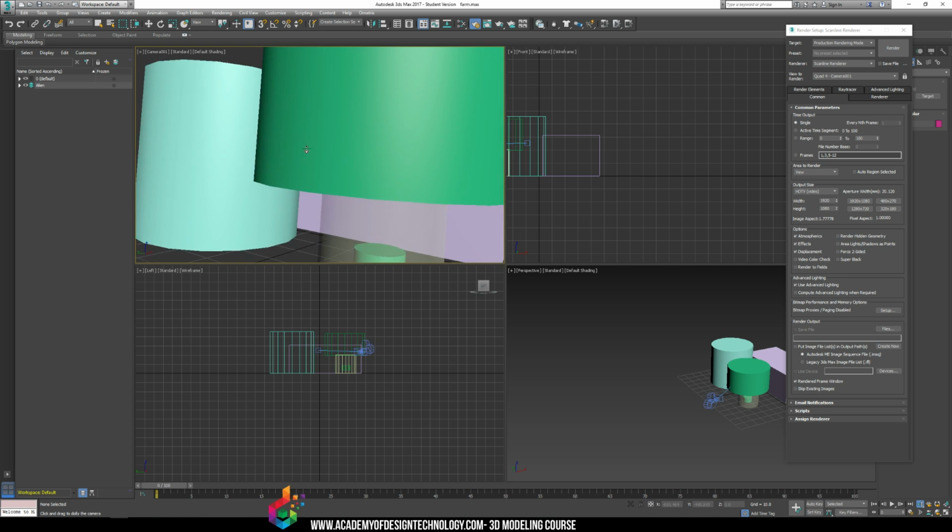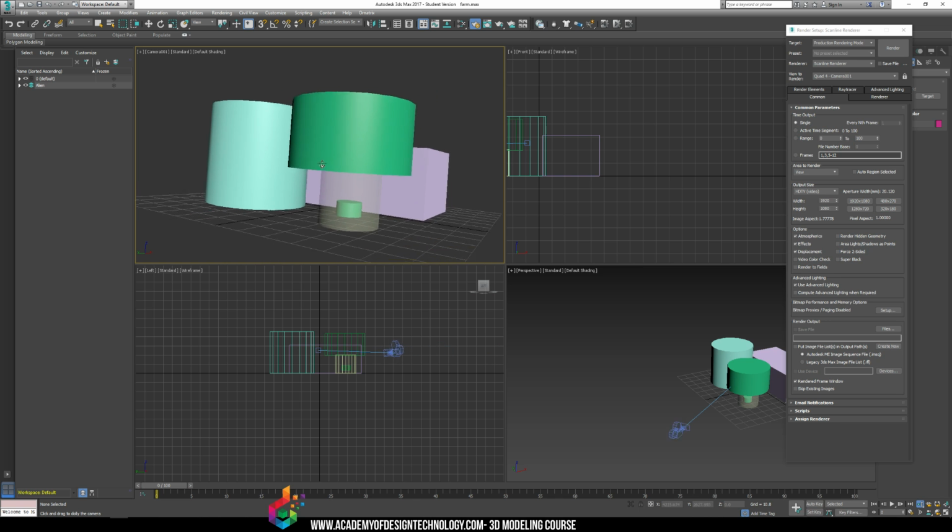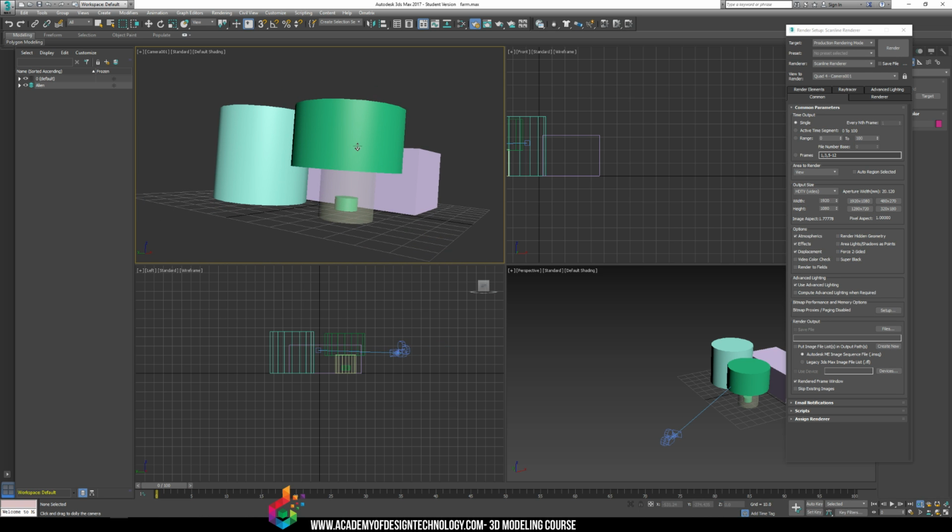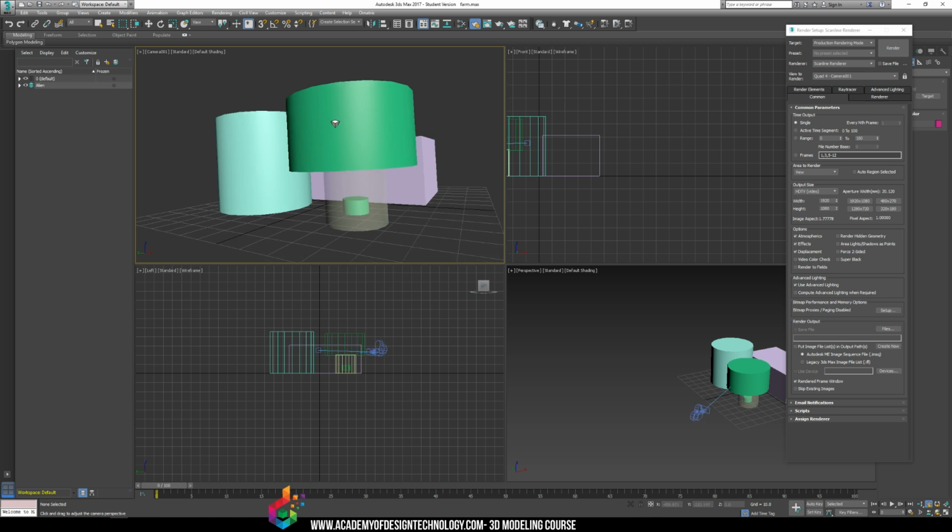You can dolly the camera so you can zoom in and zoom out here. All your camera tools are at the bottom right down there. So set up your camera however you feel like you want to set it up to create an interesting render. And don't be afraid to change where your objects are in your scene to match that as well. I love playing with the perspective tool. I think it adds a lot of uniqueness to renders and makes them actually tell a story.